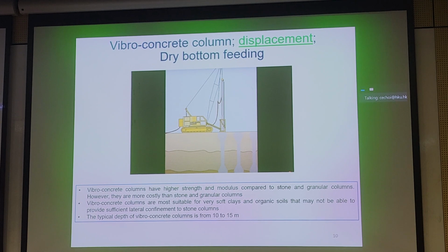If you are working with piles right now, you might understand that there are two main components with columns, either bearing capacity or skin friction. In this case, we create this special shape to increase bearing capacity of these particular columns, and you would repeat this process until you get a composite foundation of soft soil and concrete columns. Now the typical depth of this is not particularly impressive. You're still working with a relatively thin layer of marine deposit here. Thickness is anywhere less than 15 meters.